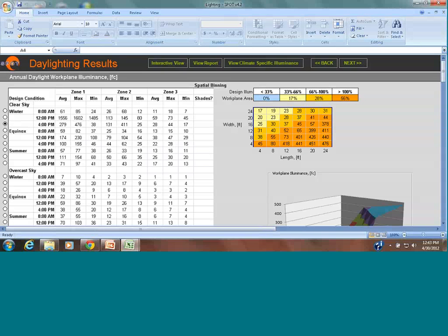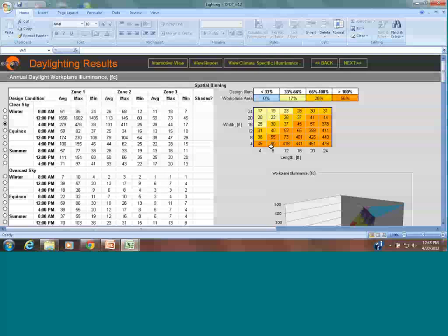So again, this is something that we have to be very careful. If your teaching wall is on that side, which is the east side of the classroom, you have a problem, because what we are looking at is the sun penetrating from the west at 4 o'clock. So you will have a glare problem at the teaching wall right here.